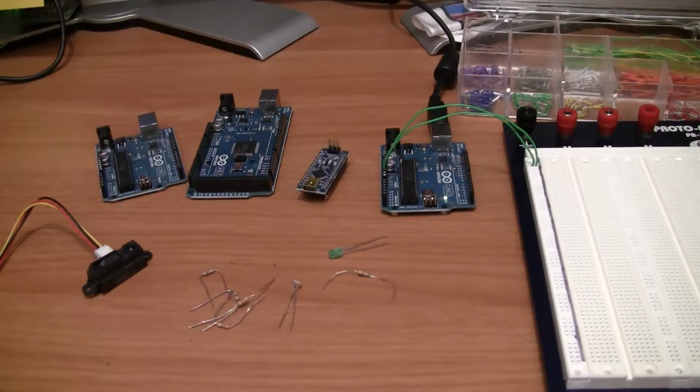You can set the reference voltage that you use for the analog inputs on all these Arduino boards. By default, it's set to 5 volts or 3.3 volts on 3.3 volt Arduino boards, but here we'll just be working with the default 5 volt boards. You can also set it to an internal 1.1 volt reference, although that's not available on the Mega. And on the Mega, you can use different commands to set it to 1.1 volts or 2.56 volts as a reference. You can also select your own voltage reference by setting it to an external value, which you input into an analog pin on the Arduino.